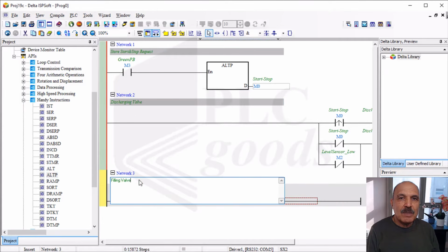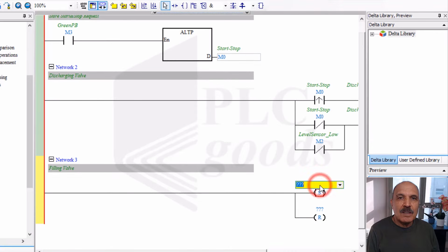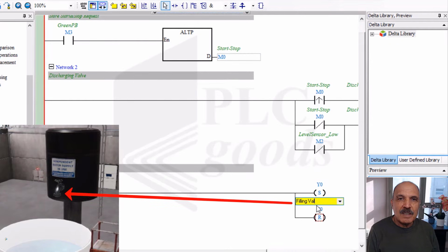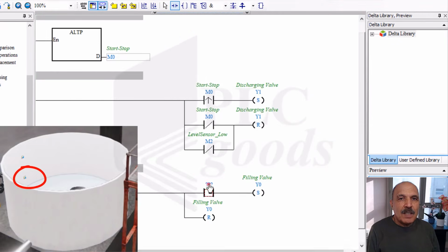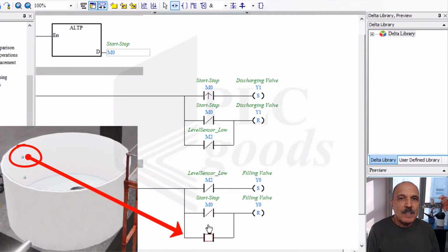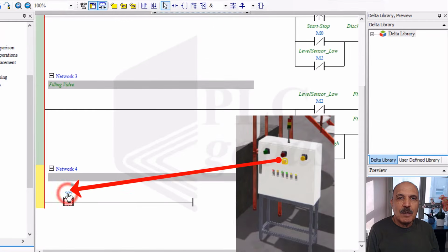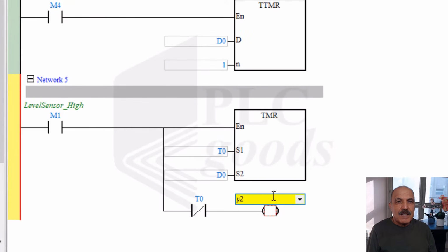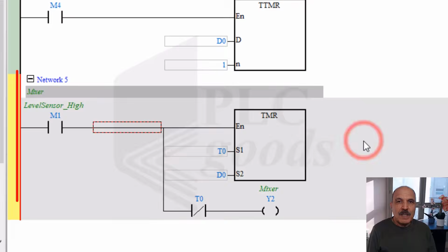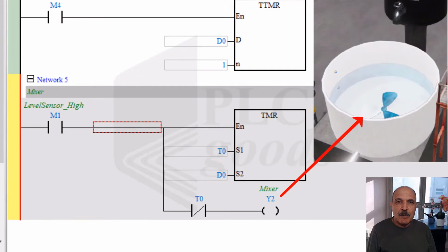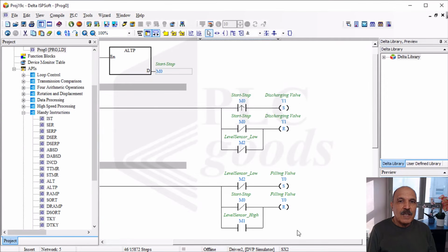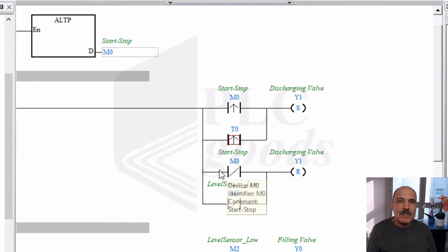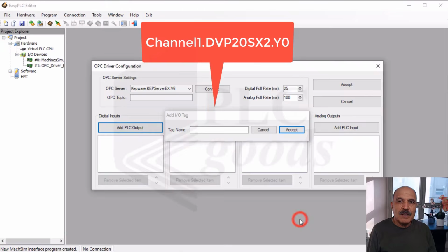A second push-button influences the mixer runtime during cycles. A TTMR instruction tracks expired time for a mixer activation. The tutorial explains that during presentation in WPLSoft, the program can be adapted to ISPSoft software. Self-learning tips are provided, spotlighting using the help window and referring to the comprehensive WPLSoft user manual accessible on time.